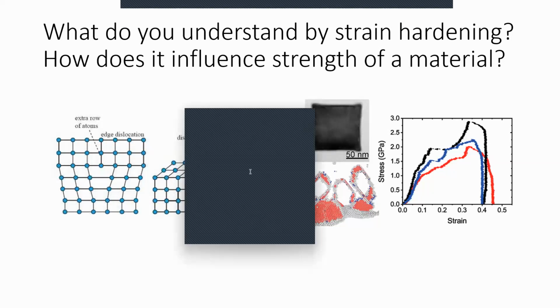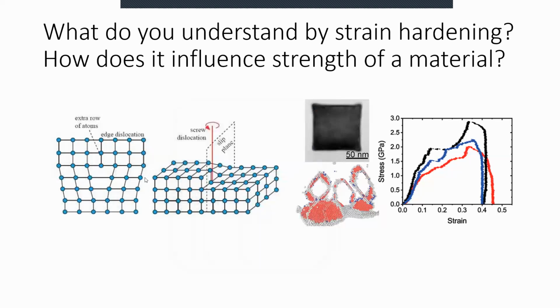No, Rajesh, what you are saying is one of the parameters of strengthening, that depends on grain structure, the grain size. If you have a smaller grain size, then you have a greater resistance to deformation. That is explained by the Hall-Petch equation. This is something called the dislocation effect, which gives rise to strain hardening. What you are saying is a grain size effect.